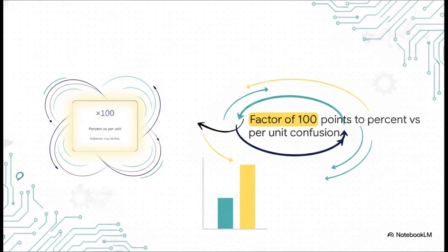And that brings us to our third common error signature, being off by a factor of exactly 100. When you see this, it means someone, somewhere, confused percent impedance with per-unit values. It's an incredibly easy trap to fall into if you're rushing. The big takeaway here is that these specific error sizes aren't random. They're literal clues telling you to rebuild your ledger, not just blindly rerun your calculator.